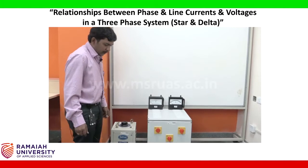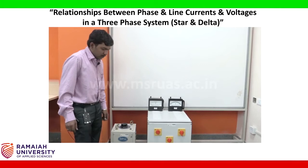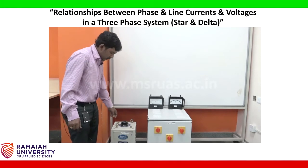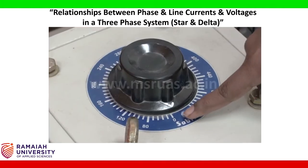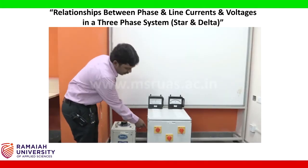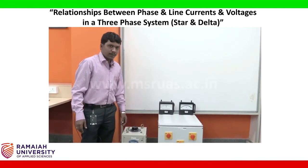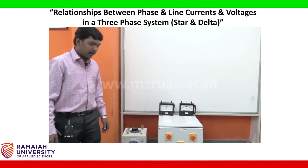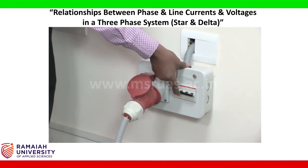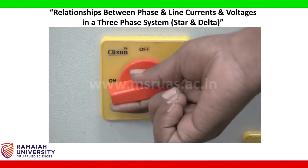With this, the experimental connections are finished as per the circuit diagram. Before conducting this experiment, make sure that the variac knob is in the 0 position and the load is in the switch off position. Let us start the experiment. First switch on the power supply. Now switch on the 3-phase AC supply. Now switch on the load.